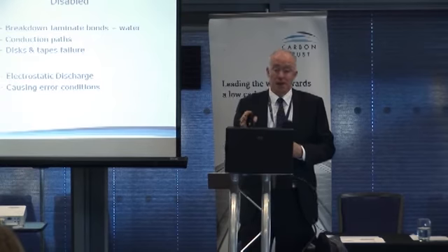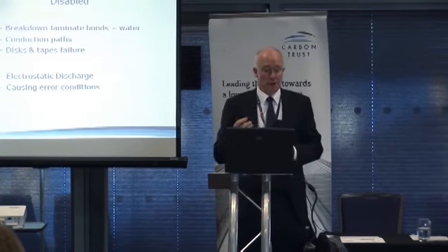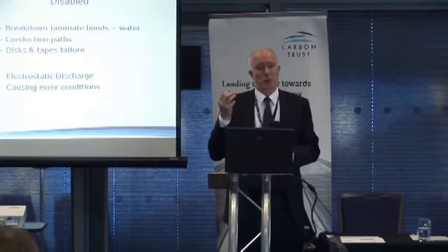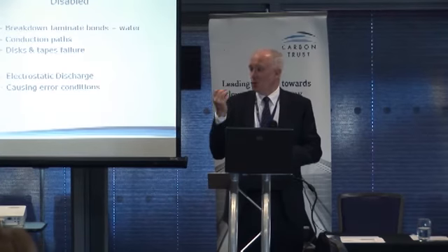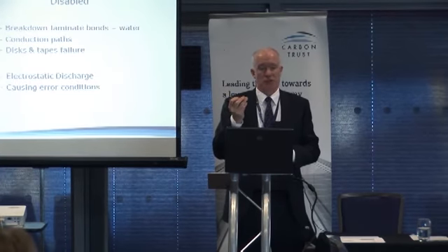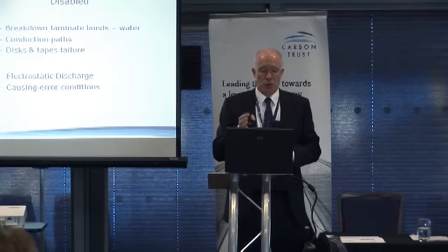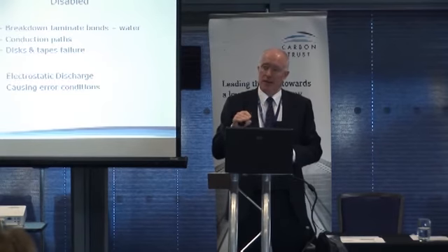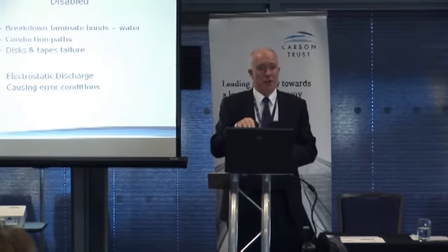Humidity is an issue that you can have problems with. If you've got high humidity, then the moisture in the air can cause tracking within the transistors and therefore cause failure. So if you've got very high humidity, you can have failures. It doesn't often happen, it's very rare.